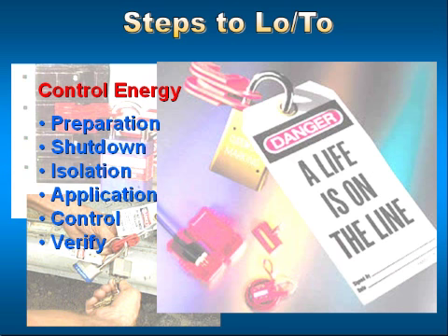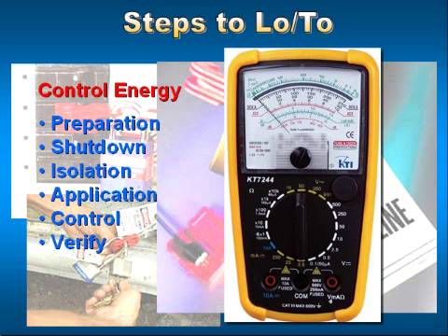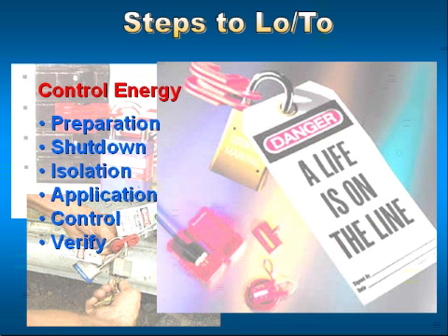Verification, for all intents and purposes, should be done through instrumentation, i.e., if it's an electrical source, put a multimeter on it, a direct reading instrument. If it's a hydraulic pressure, use a gauge system, a direct reading instrument. All too often in today's society, with a quick, easy way of doing things, they have devices now, for electrical energy, that you can simply pass near it, and if it comes near an energized circuit, it starts flashing.